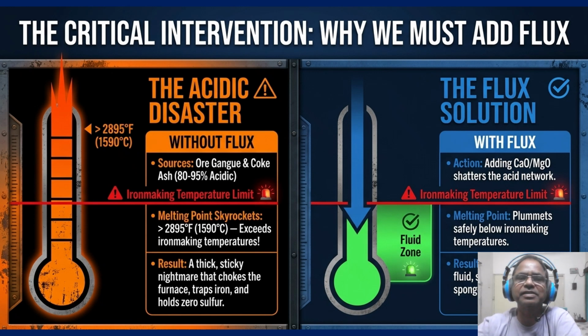In practice, acid slag, that is high silica, has a melting point of more than 2800 degrees Fahrenheit, is very viscous, and has poor desulfurization. As for basic slag, with CaO/SiO2 near 1.1, the melting point is 2450, viscosity 2 to 5 poise, about as fluid as heavy motor oil, and excellent sulfur removal. Operator yardstick: your daily target is B2 between 1.05 and 1.20. That's the sweet spot, fluid enough to drain from the hearth, but not so aggressive that it eats your refractory.